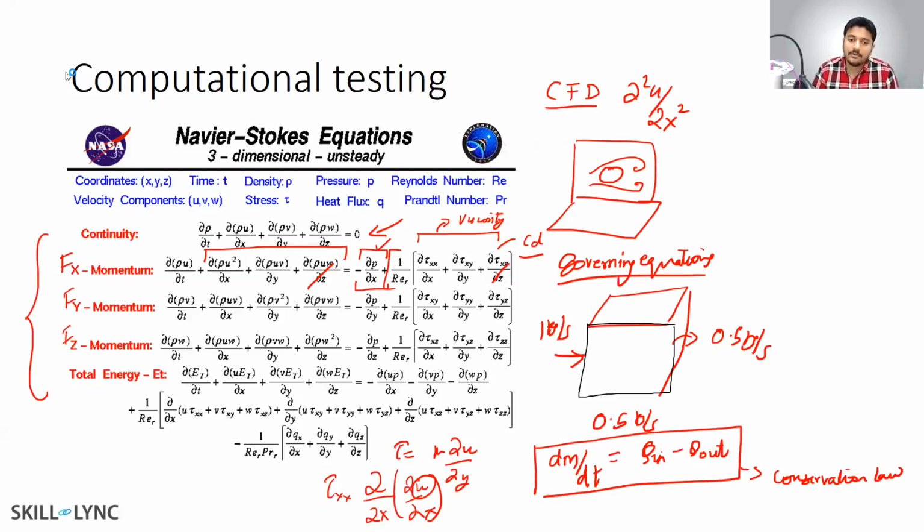So with respect to CFD solvers, there are a lot of equations, and especially there are two equations that pretty much everyone remembers. This question is primarily intended towards guys who have already done CFD simulations. I'll give a clue. There are two terms. The first term maybe is K. The second term is K dash epsilon. K epsilon equation or K omega. Sure, why not? What is this equation for, Shahzad? This equation is for turbulence, and we call K and epsilon conservation equations, correct?